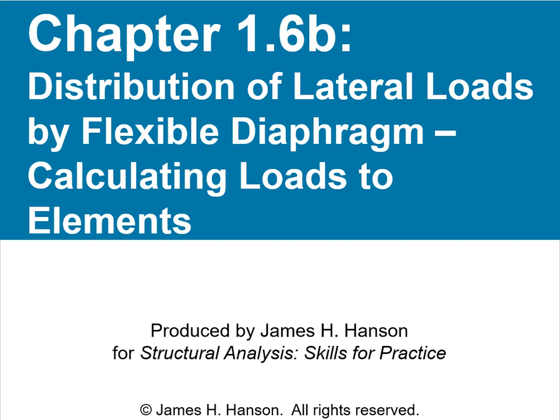Once we know how much loading is being applied in plane to the diaphragm, determining how much of that load goes to each lateral load resisting element depends on whether the diaphragm is rigid or flexible. We cover rigid diaphragms in a later chapter. Here we are going to discuss how to analyze flexible diaphragms.